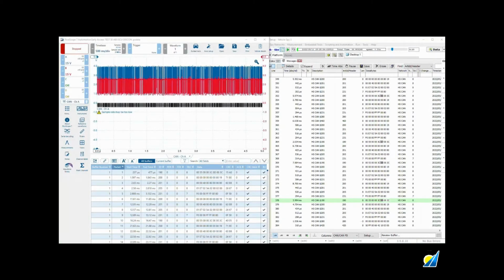Now, what we could say was that those ECUs were transmitting, and that got me thinking, what could they be? Because if they're transmitting, if they're online, then during that point in time, maybe they are not responsible for that condition. So remember the ID with the lowest number has the highest priority.